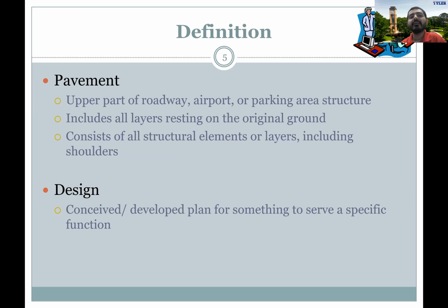When I say pavement, again, this is really the upper part of any roadway. So this is the man-made layer on top of the soil. It's not just the top layer, it's actually everything, many layers, and they're certainly different as you go up from the surface of the soil. We have what we call a sub base, and then a base, and then hot mix asphalt, which is the top layer.